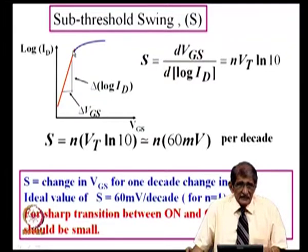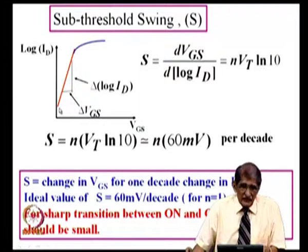I have to reduce the gate voltage by 300 millivolts. So, if the slope is 60 millivolts per decade, it has to fall by 5 decades, 300 millivolts divided by 60 millivolts. When the voltage falls from 300 to 0, the current will fall by 5 decades. That is the ideal case.